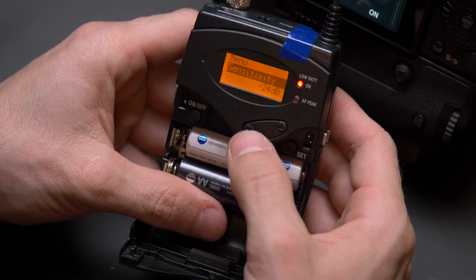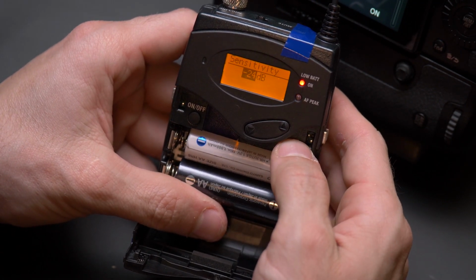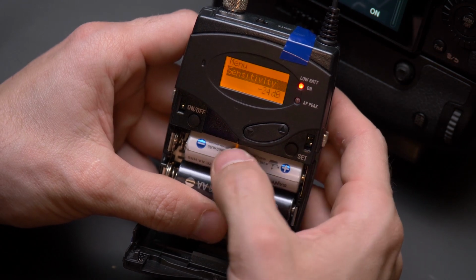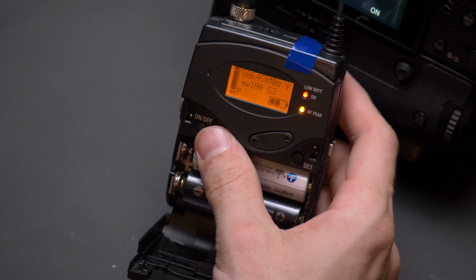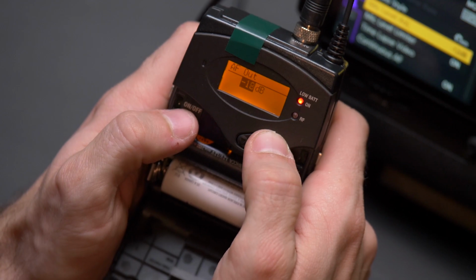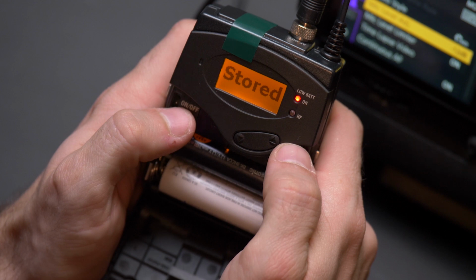So the settings that we have found sound best for the Sennheiser transmitter, where the microphone is plugged into, is minus 24 decibels. That's loud enough to allow a good clean signal, but it's low enough to where if somebody gets really loud or starts yelling, it's not going to clip the microphone. For the Sennheiser receiver that's going to receive the signal from the microphone and then send it to the camera, we have that set to 0 decibels. By setting the receiver to 0 decibels, it's going to amplify the signal enough, but not amplify it so much that the camera is going to receive a clipped signal.